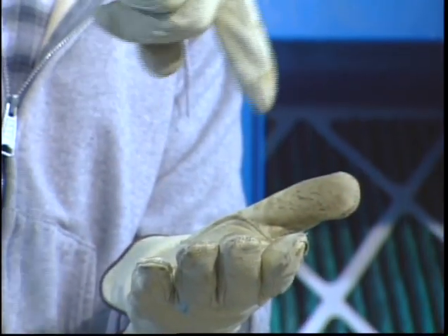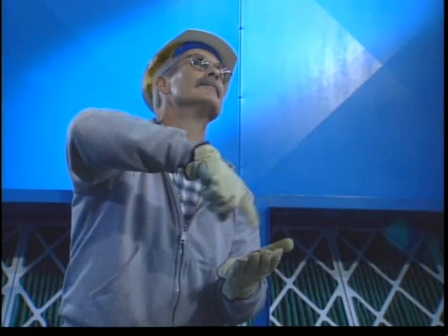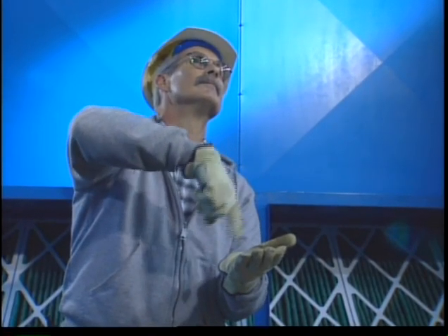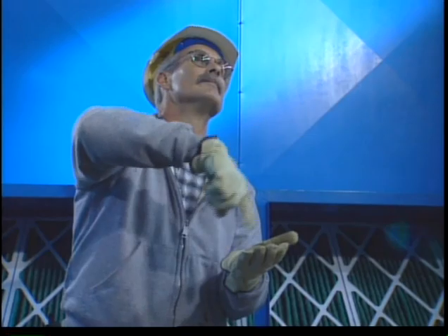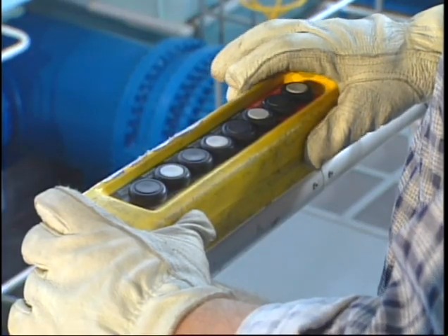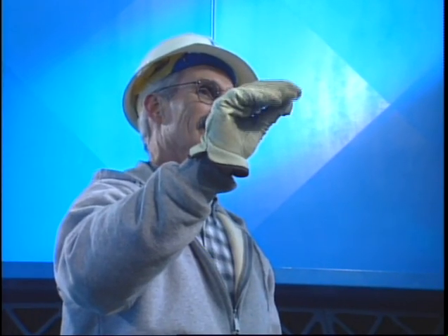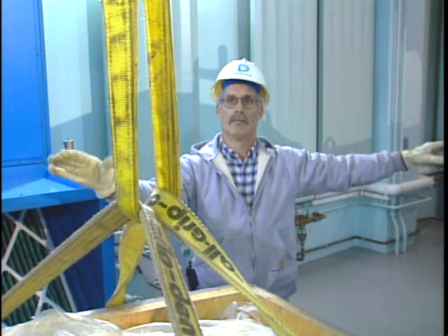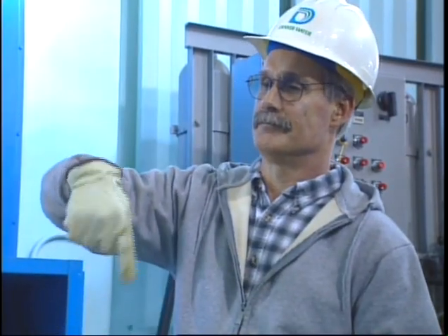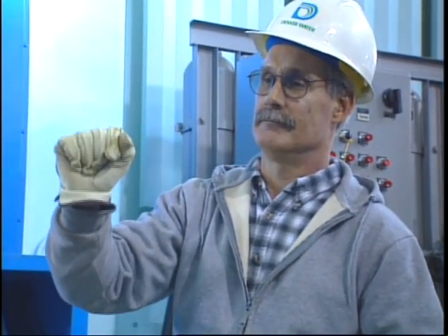When it's important to move the load slowly, the signal person puts a motionless hand directly in front of, above, or below the hand giving the motion signal. Thumb and fingers pressed together also signals the operator to move slowly and carefully. Stop is with the arms extended. Some signalers use a closed fist to signal stop.